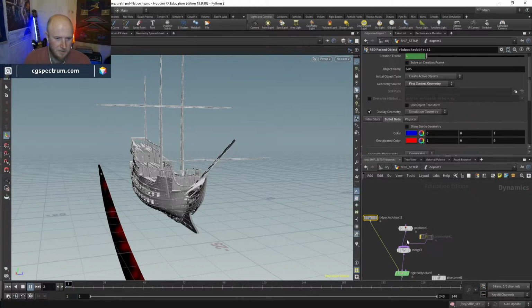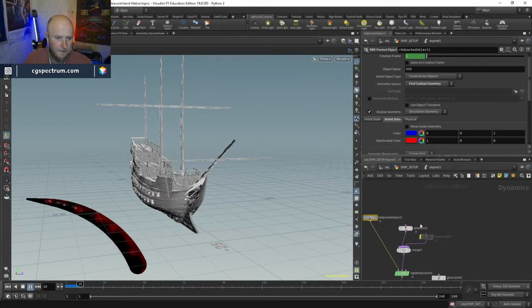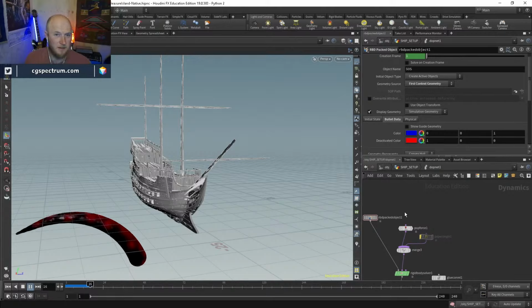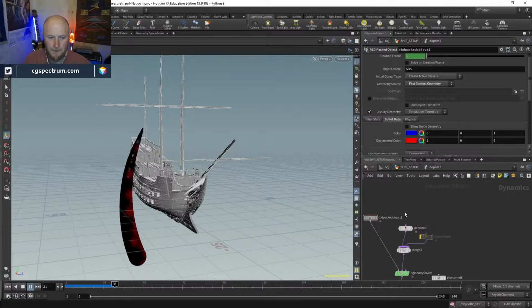Fast-moving colliders are always problematic in lots of simulation contexts. They're always troublesome. You can do things like slow the whole simulation down, like run the simulation at half speed, including the collisions, and then speed the whole thing up afterwards. That can sometimes work too. As you can see, it's moving much slower now.